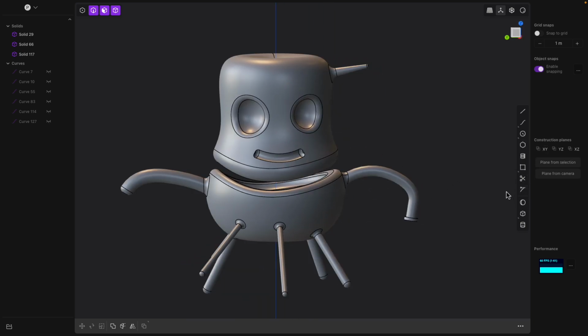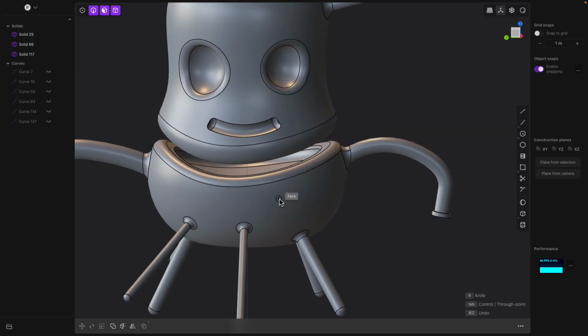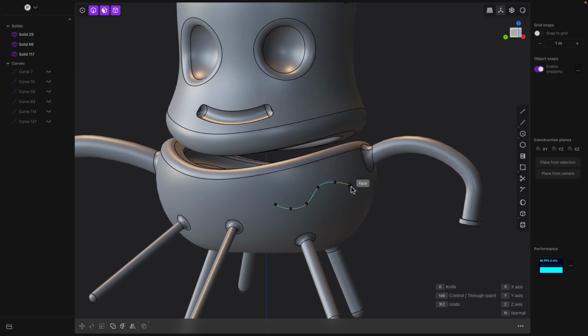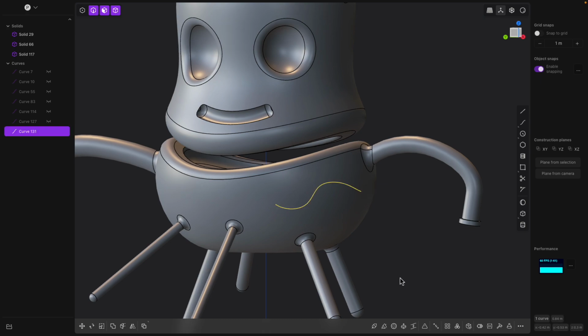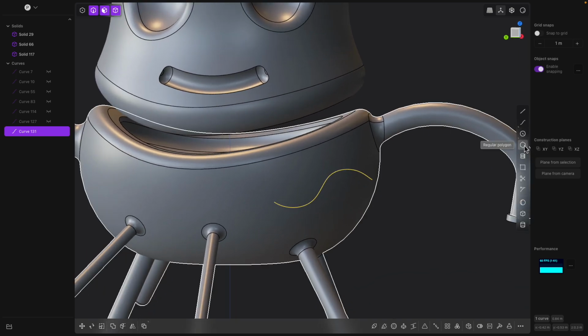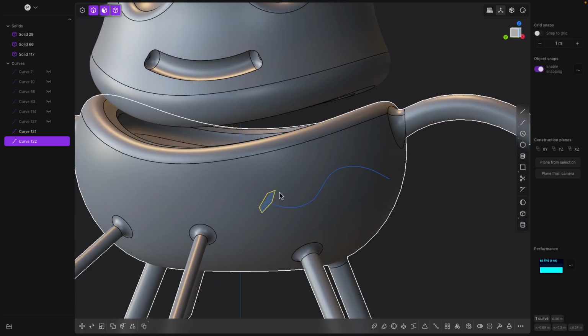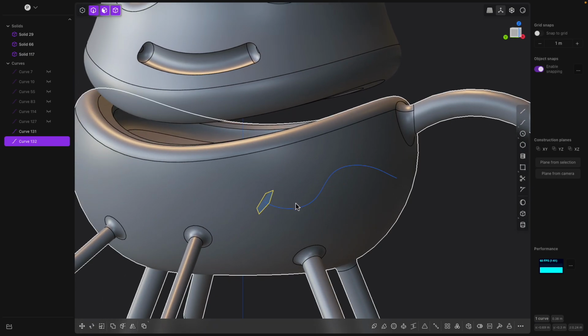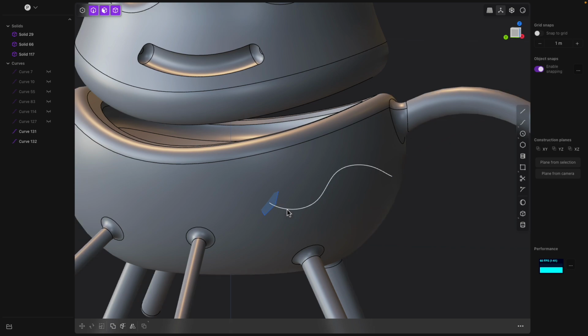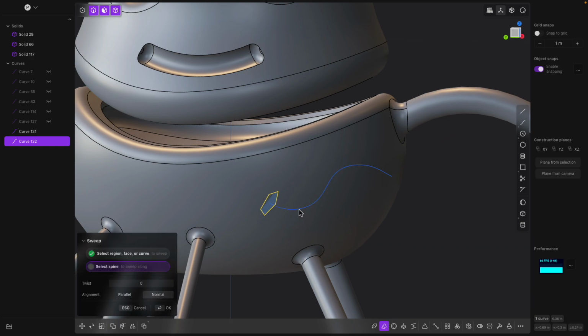I haven't touched all the cool things these guys can offer, you know, like we didn't use sweep. I was gonna use sweep. I believe you can just attach. Yeah, see, I was attaching this pentagon on this guy, so we can actually do the sweep operations. Sweep, select the curve, and then select the spine.